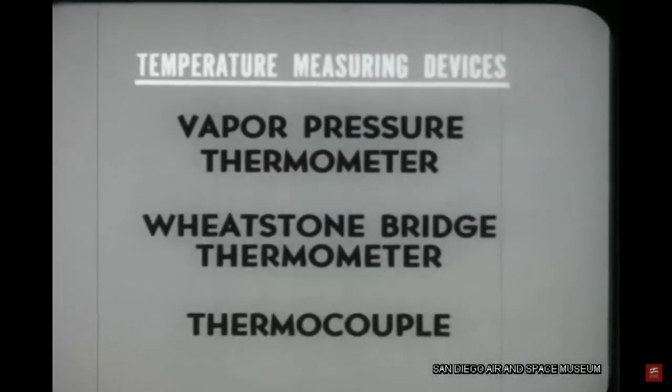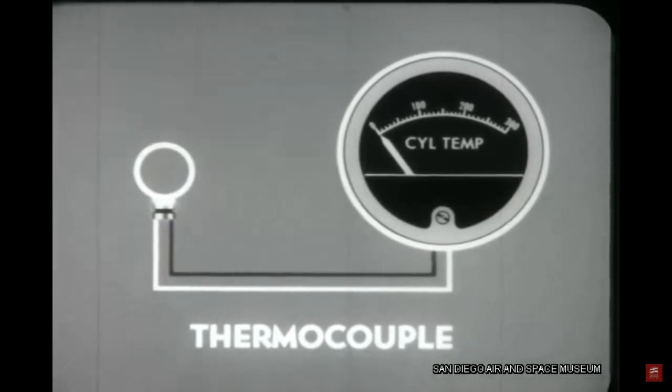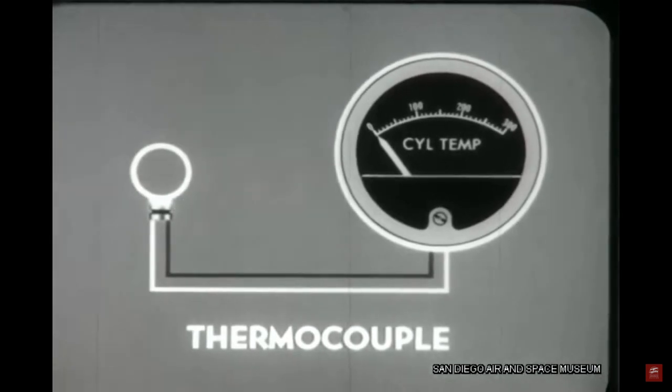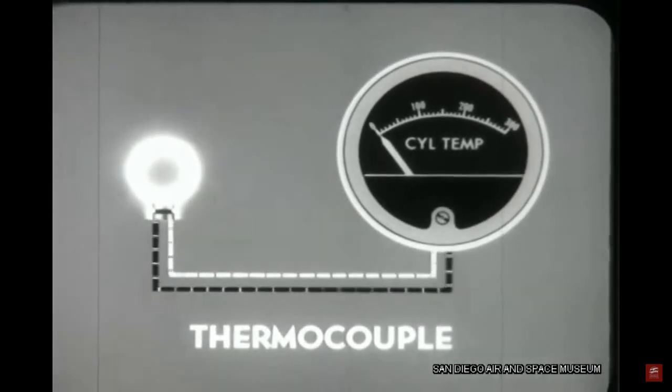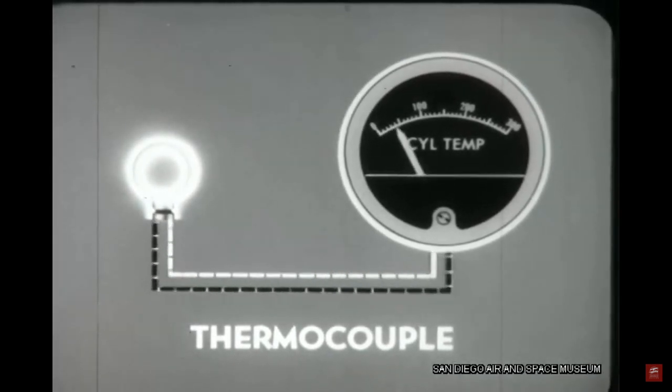Our third temperature measuring device, the thermocouple, is based on the following electrical principle. Two wires composed of two different metals are firmly joined together at one end. The opposite ends are connected to a sensitive electrical meter. When heat is applied to the joined ends, electrons will flow through the wires, and their flow will be indicated on the meter.